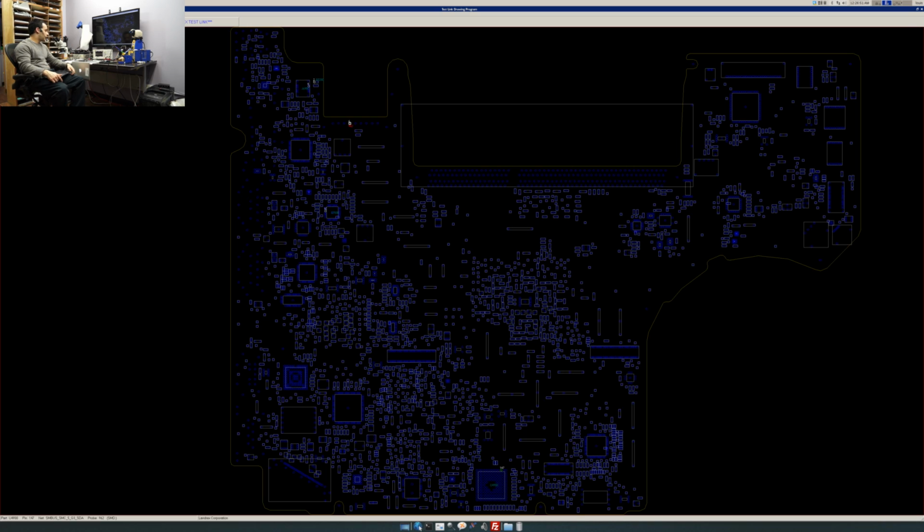So I decided, okay, I'm going to do this the hard way. I removed the battery indicator without removing the connector. Still same thing. I removed U7000 because it was next on my list, and the short went away completely. Thank God it went away completely, because if it didn't go away completely when I removed U7000, that would have meant that the SMC was bad, and the SMC is a chip that you replace by removing a bunch of balls that are like 0.3 or 0.25 millimeters and putting them back on.